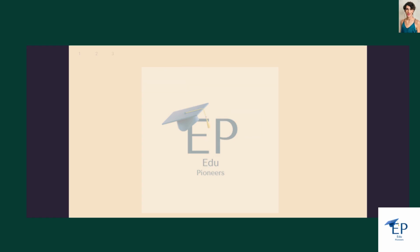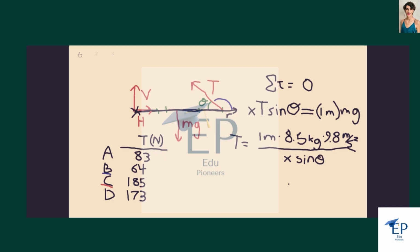So now, as you might guess, we're going to use our last static equilibrium condition. The sum of the forces in the y direction equals 0. And if we look back at our free body diagram, we've got 3 different forces in the y direction. Now we've got the vertical component of the hinge force that we're looking for. We've got the vertical component of tension, which is T sine theta. And we've got the weight going down.